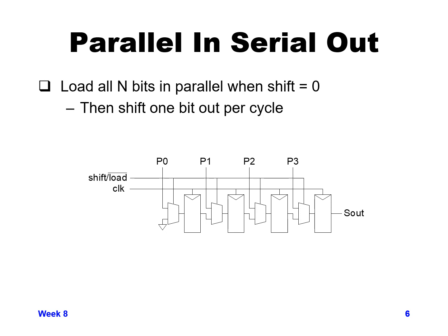And so in this case, we actually need a 2-to-1 mux going into each of the memory elements, because we need to know whether we're loading the values in parallel or whether we're shifting them out. When we're loading them, we choose the top input to the 2-to-1 mux, and we then of course need a controller for each of the 2-to-1 muxes that's controlling whether we're doing the shift or the load.